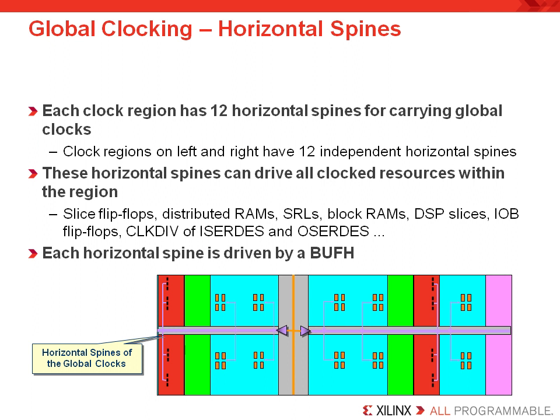Now this slide shows a close-up view of a 7 series FPGA's clock regions. Each clock region is 50 CLB rows high and about half the width of the device. Each clock region contains 12 BUFH buffers. Each BUFH can then drive any clock routing resource into that clock region, such as registers, shift registers, block RAMs, DSP slices, etc. You should also note that any 12 of the global buffers, that's the BUFGs, can drive the BUFH resources in each region. But basically, we're trying to describe to you that the global clock routing resources are segmented into BUFHs.